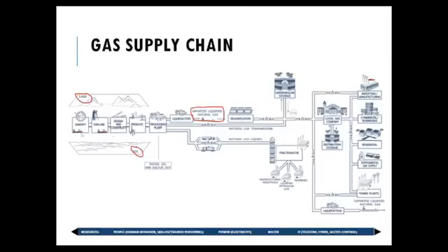So the process is similar. The supply chain: identify, explore, design and construct, produce, processing plant. In the processing plant, the water, oil, and sulfur are taken out. If it has to be transported to a different location, as it occupies a huge amount of volume, it is liquefied at minus 160 degrees centigrade. Then it is transported, and after it is received, it is regasified. Then it is sent, depending on how it has to be, to the local gas company, distribution, storage, industrial, manufacturing, commercial, residential, supplemental.